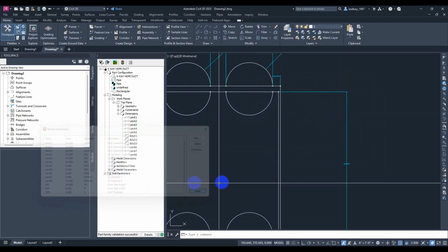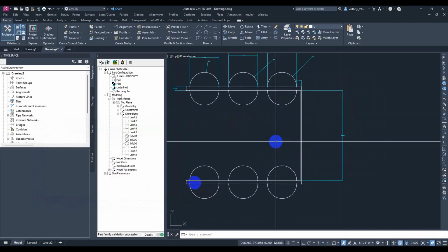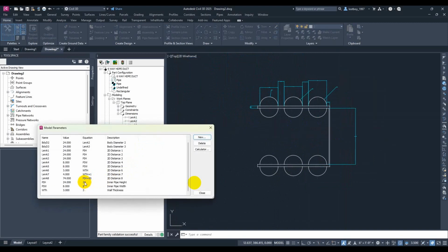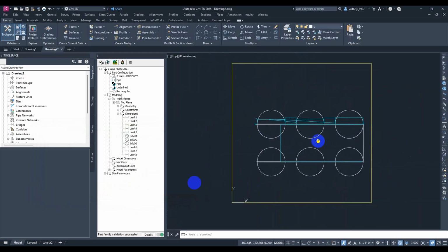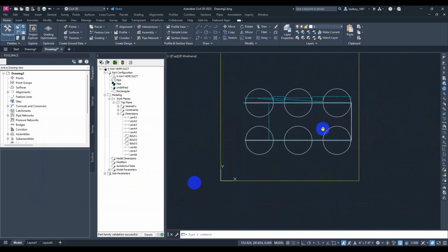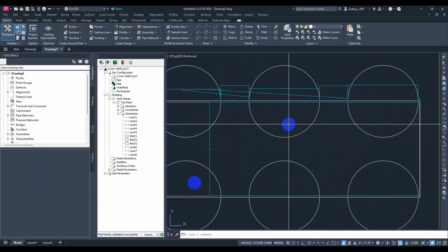Here 50 is a big number, but actually it's okay for the dimensions that I need. Like if I'm using a 150 millimeter pipe duct diameter, it will be very good. And you can change it later, and you can control all these dimensions later. As you can see, now it's looking good. 150 pipe diameter, 6-way, all tied together.